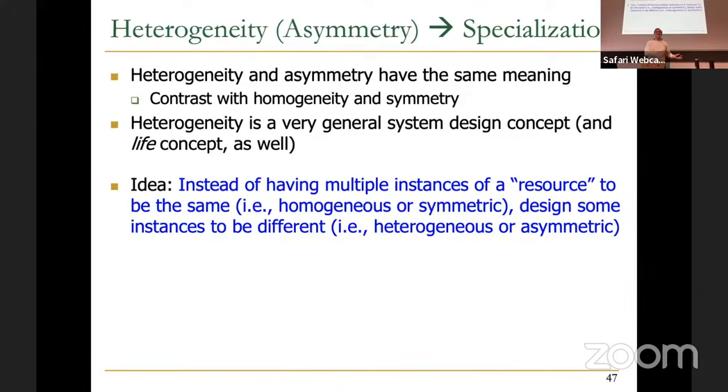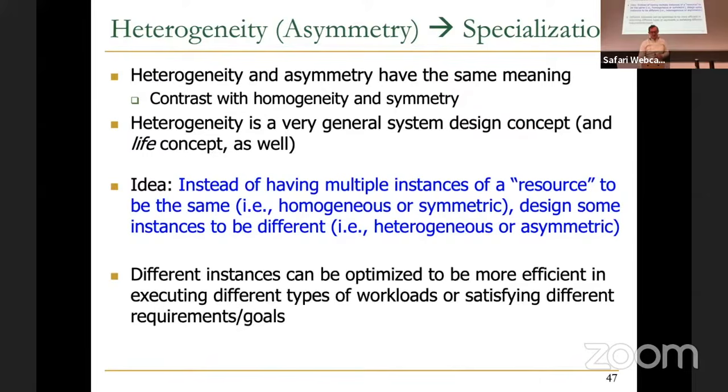But then you can also design things to be heterogeneous. And we have also seen that, right? We've seen, for example, tiered latency DRAM, right? Adaptive latency DRAM. Adaptive latency DRAM actually is exploiting natural heterogeneity, but tiered latency DRAM is really designing a subarray to have two components. One component is fast, the other component is slow. Now you added heterogeneity. That's a very conscious design. Okay, so you can design heterogeneity or you can exploit heterogeneity that's already present.